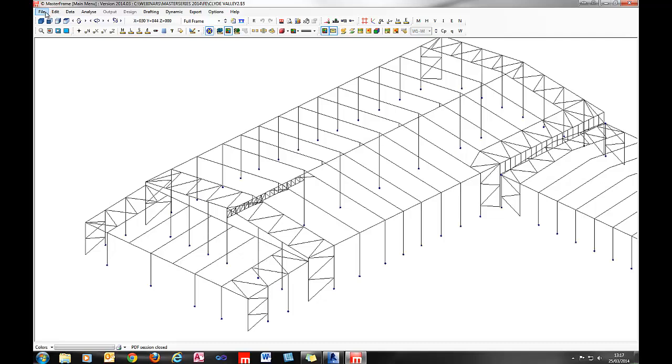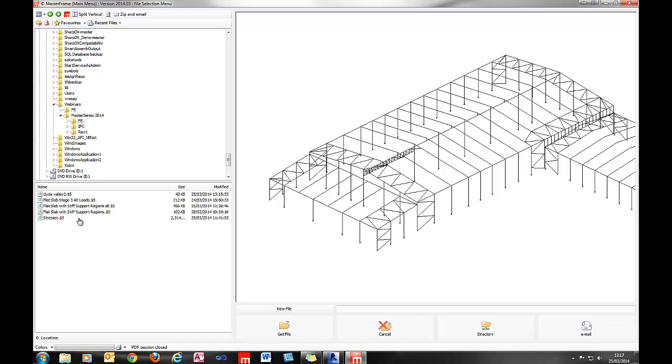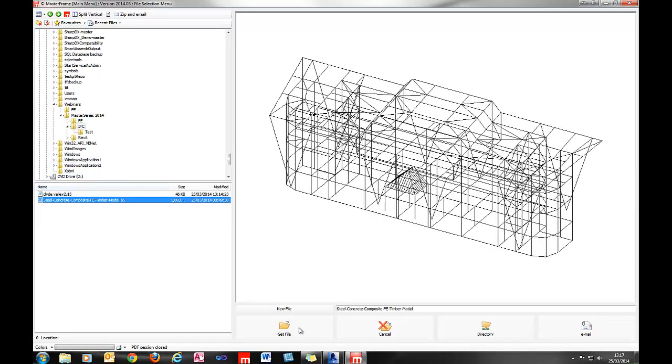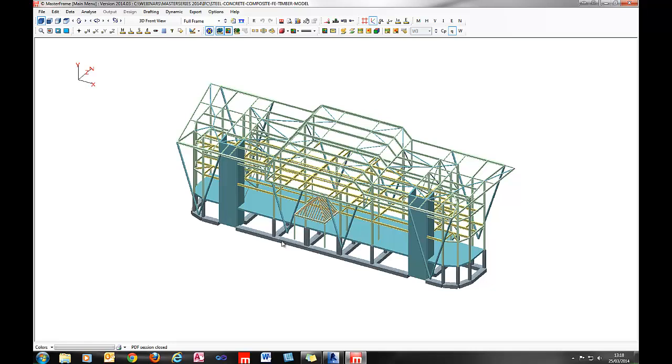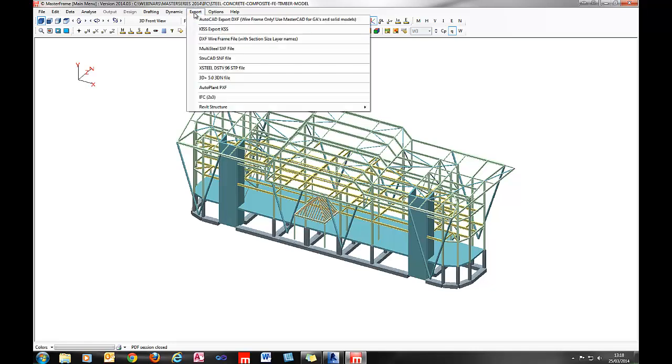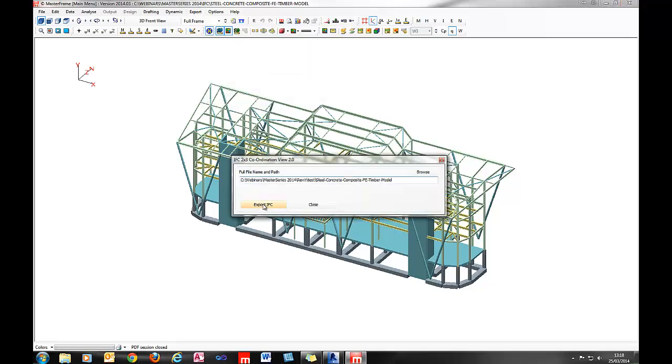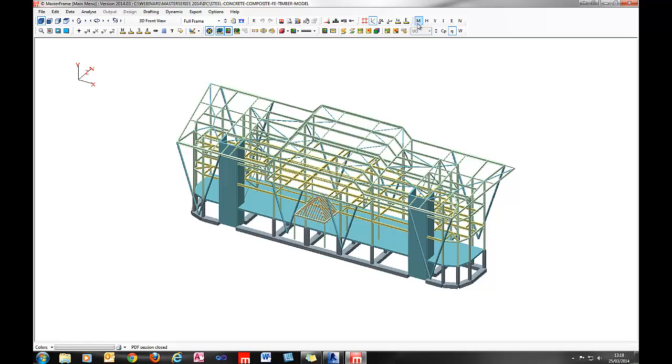Now, I want to show you something else just on this score of IFC, and that's the exporting in IFC as well. So if we come into here, IFC, I have another model here. You've seen this model perhaps on different occasions and different webinars, but we've got a nice model here of a mixture of slabs and walls and different types of materials. Just to show you the exporting procedure, very simple: IFC and simply export IFC, and that will export the entire model.